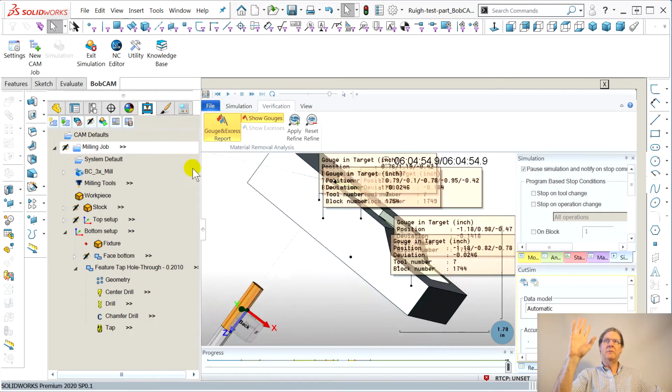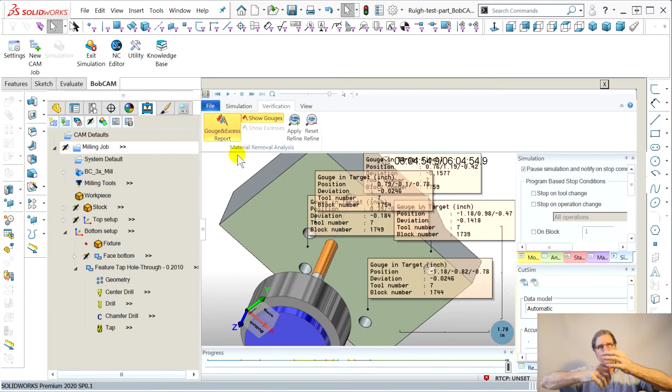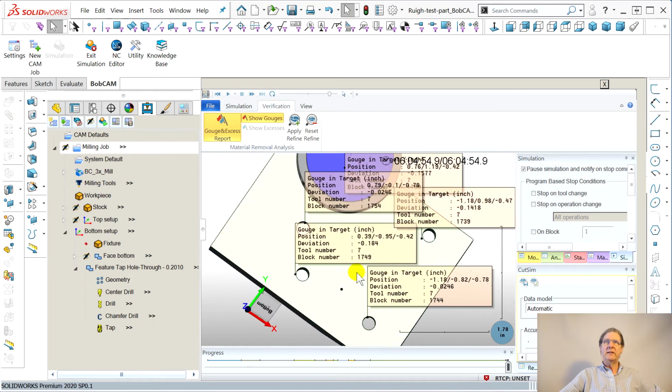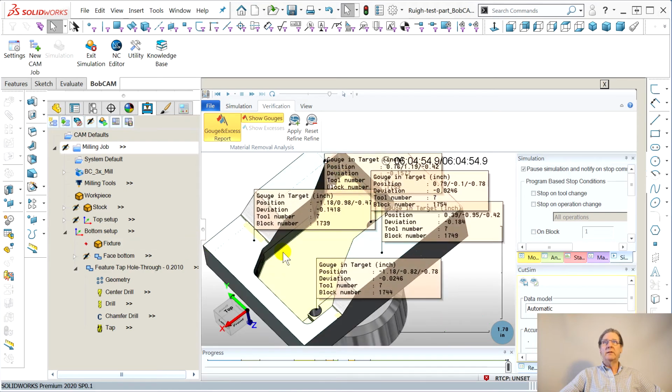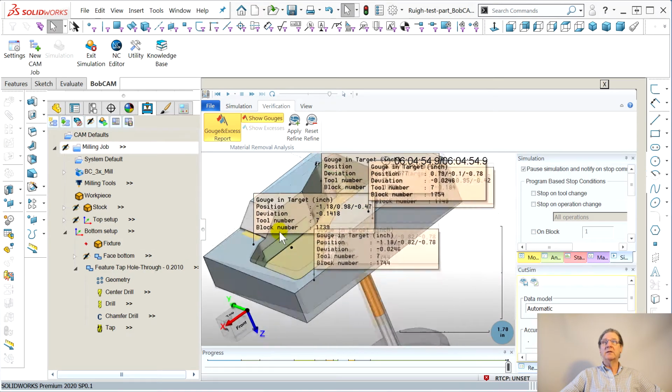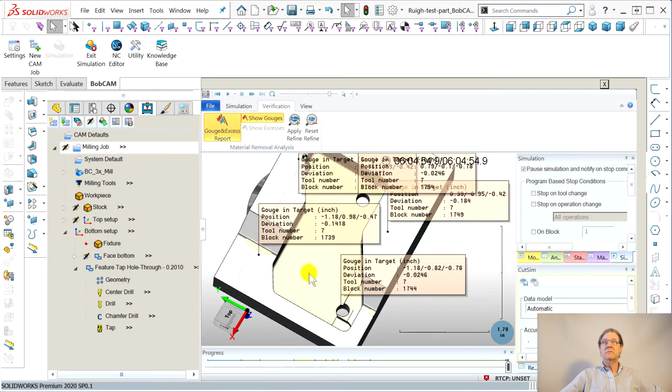This is the same problem in that the tap is defined as 0.25 outer diameter. The holes are 0.201, so that's the tap drill size. So as far as the program's concerned, you gouge through that model, because the model was 0.201, but when we simulate our tap, we use the outer diameter of the tap. All the programs have been doing this. You kind of expect it. You don't get too worried. It doesn't show excess material anywhere else. So that's a win in my book.